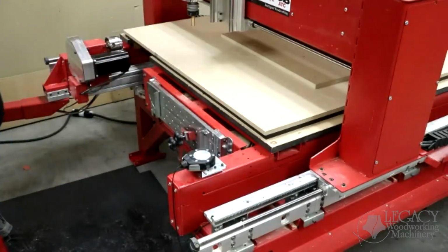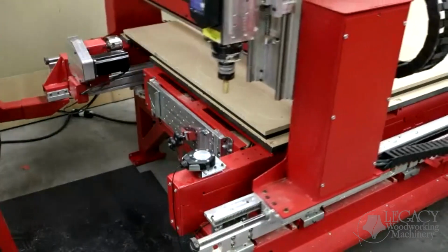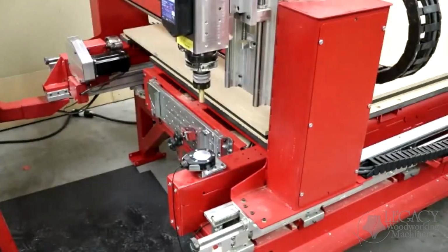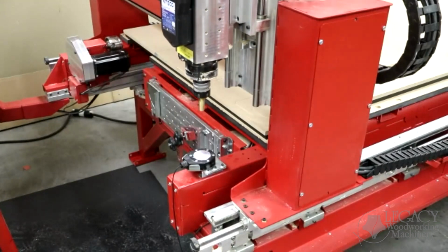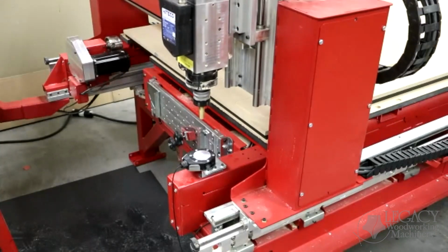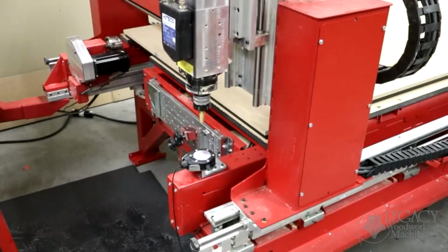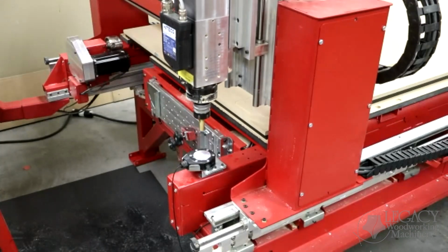And I put my longest tool in here that I called for, and then I press go. Now you'll notice it's probing the entire distance because it doesn't know how long this tool is. So it's just going to probe forever. And when it finally gets to the pad, it's going to set that rapid Z a 1/4 inch above the pad.